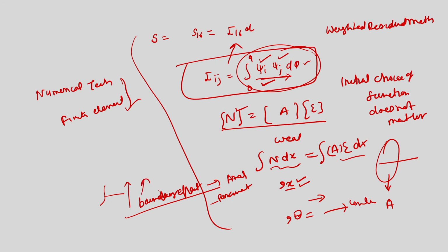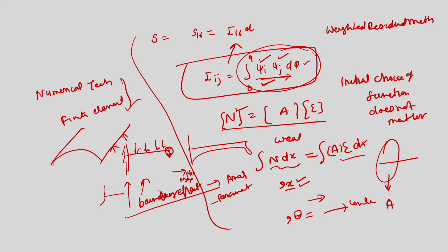What do we mean by boundary effects? When it is simply supported, there is no effect of the boundaries, but when it is clamped or free there is. Let me explain with the help of a cantilever beam. If a cantilever beam is subjected to such a loading, then at the free edge, nxx needs to be 0 because it is free, and the moment needs to be 0. If you want to see the variation, there may be some moment. So, near the boundary it dips, making some effect, it does not go smoothly.